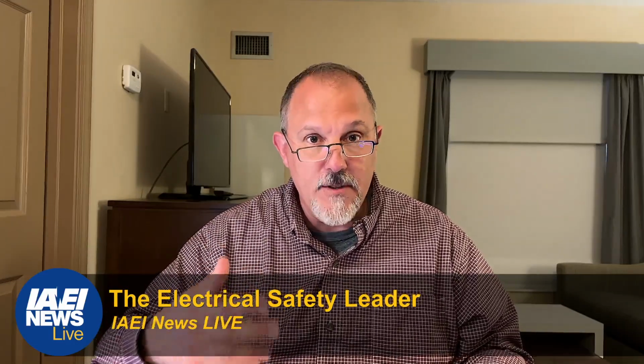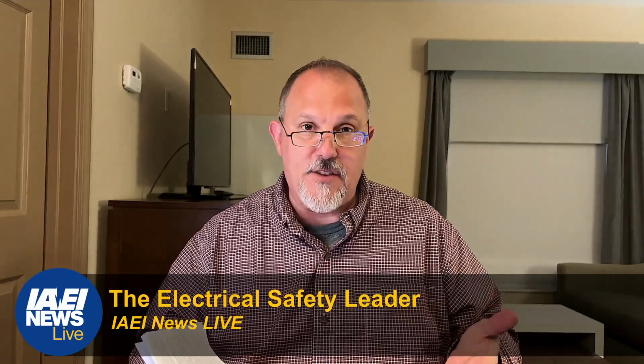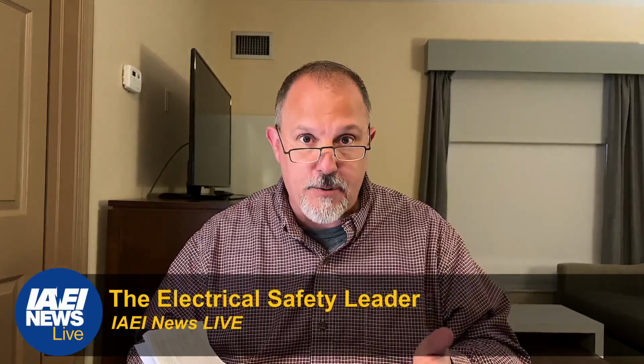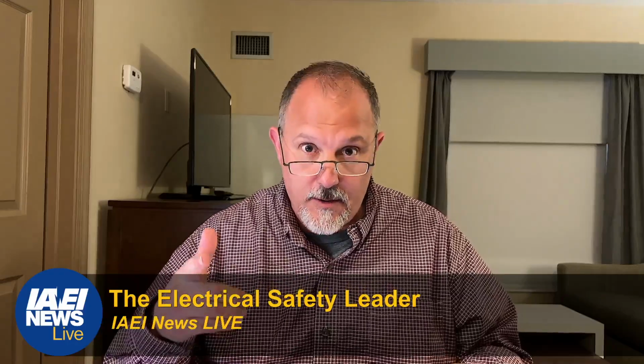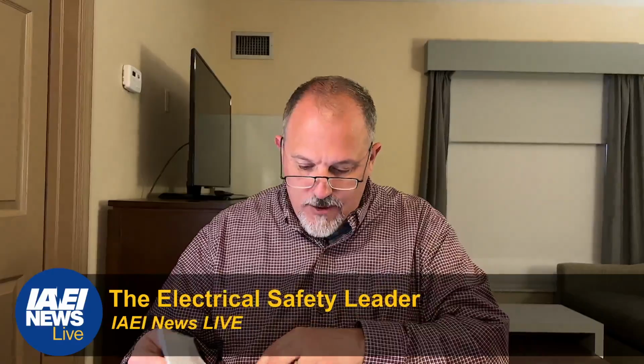Now, my point and reason in going to 240.7 is twofold. One, I don't necessarily need to tell you in 210.8 that a listed Class A GFCI shall provide protection. All I have to say is a GFCI shall provide protection. If I'm worried about the listing, it is picked up in 240.7. Remember, 1 through 4 apply generally. So now, what about this Class A language? Let's take a look at the definition in Article 100 for ground fault circuit interrupters.